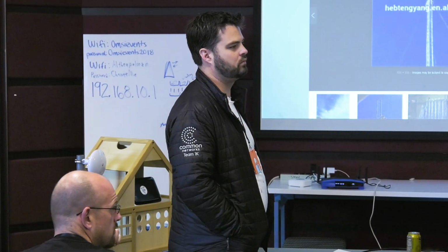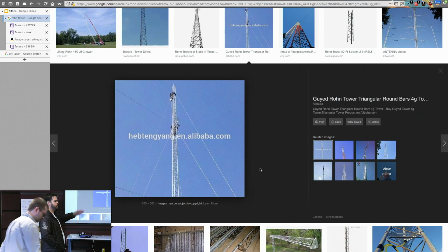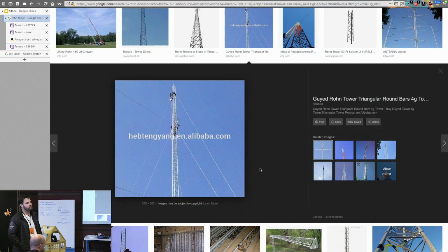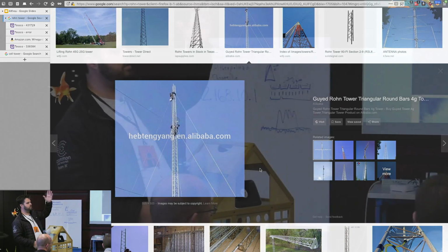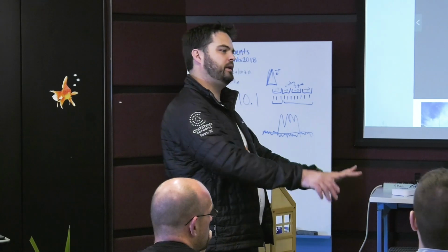Is there any effective way to deal with wobbling with home towers? To deal with wobbling? Yes. With the tower just swaying back and forth? The best thing is guy wires. If you've got a really tall tower and the top of it is going to move, you can try to bury the base deeper and harder in the cement to make the base stronger, but really the best thing to do to keep it in place is guy wires.